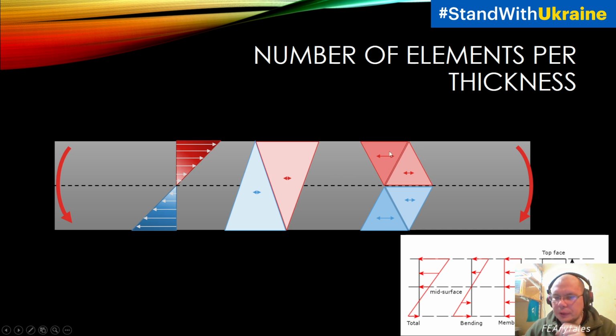So this element will have more intensive tensile stress because it has more volume here where the stress is higher, and less volume here where it's 0. And the next one will have less intensive stress, but the stress is higher than this because all the stress which we mean here is all tensile. And the same situation for compression elements.